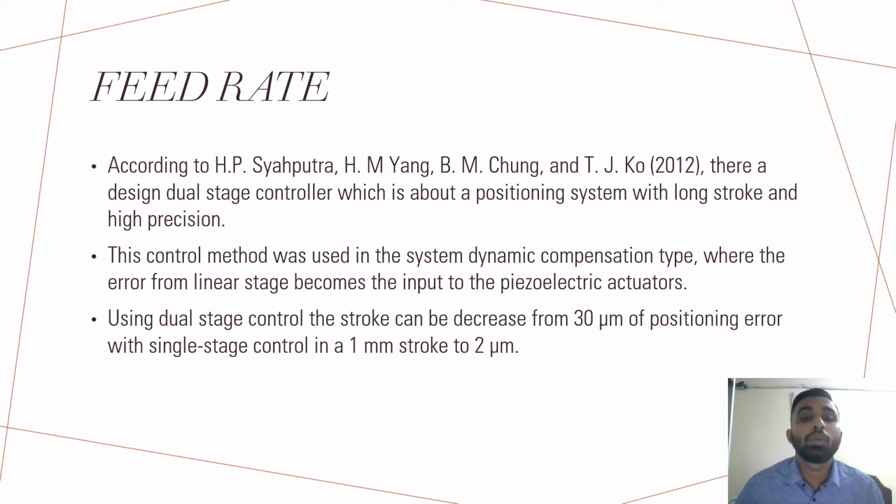This control method was used in system dynamic compensation type, where the error from linear stages becomes the input to the piezoelectric actuators. Using dual stage control, the positioning error can be decreased from 30 micrometers with single stage control in a 1 millimeter stroke to 2 micrometers.